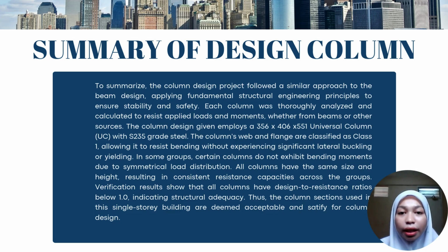The column design given employs a 365 x 406 x 551 universal column with S235 steel grade. The column's web and flange are classified as Class 1, allowing it to resist bending without experiencing significant lateral buckling or yielding.